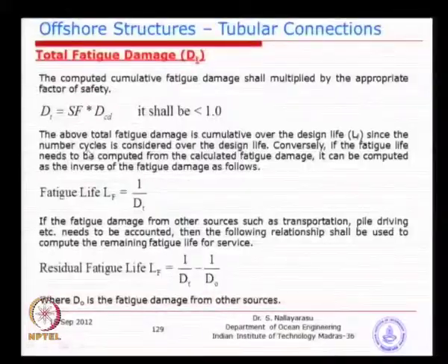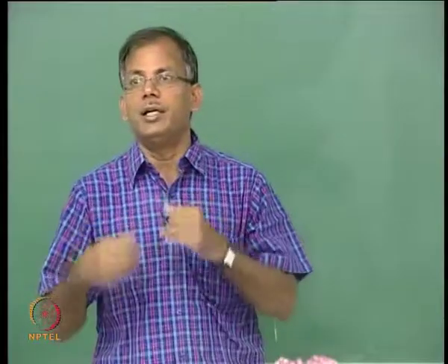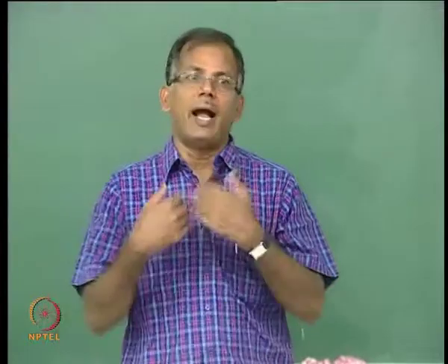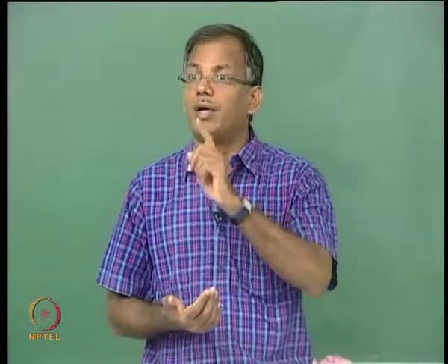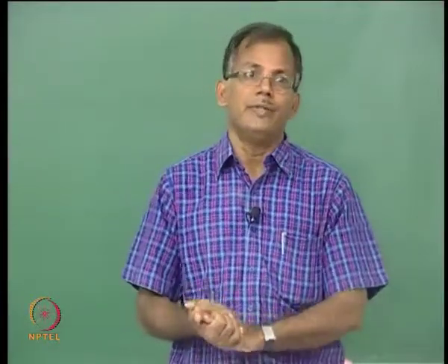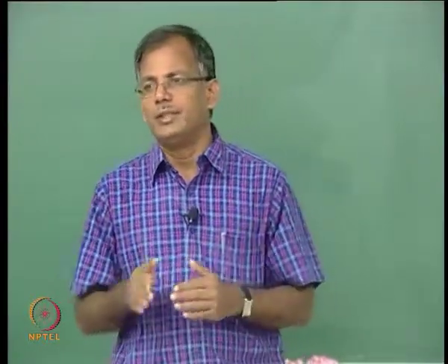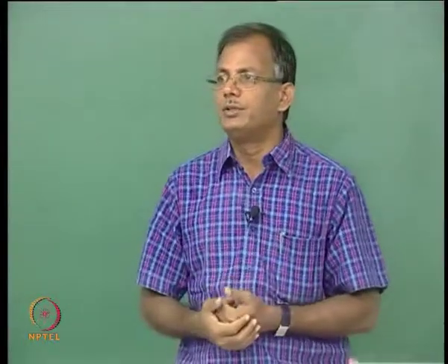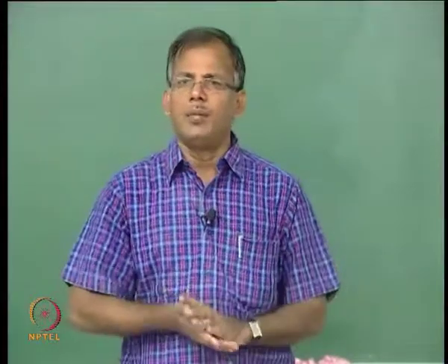That is why sometimes we may need to find out the total damage minus the damage from other sources, because before the structure reaches the site, fatigue life is already expended, that means damage has already occurred. So you have to add that. Many times transportation fatigue becomes a very major issue, especially when the transportation is longer than 2 weeks. Certification agencies normally say that if the transportation is less than 2 weeks, you can ignore it because the damage is too small, but coming from Southeast Asia to the Middle East normally takes about 4 weeks.